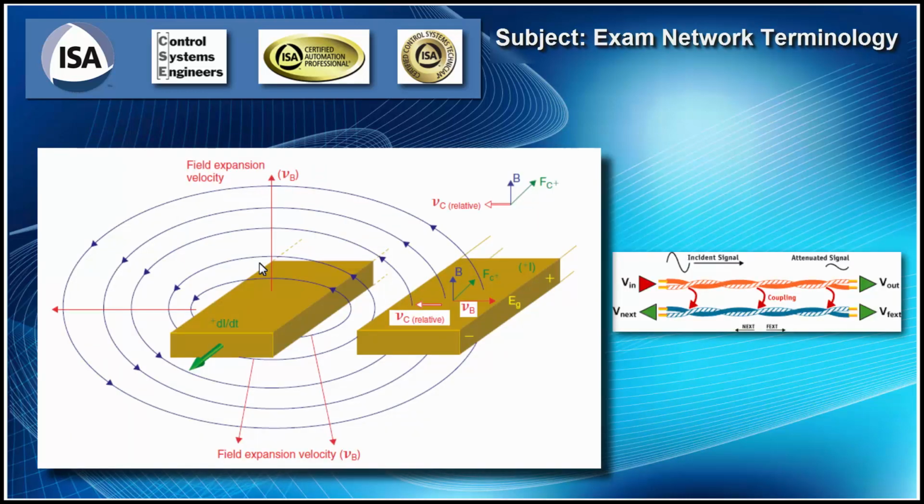The other thing I want to talk about is crosstalk, which is in the specification. Crosstalk is where you have voltage interference going into the transmit and receive, and it causes corrupted data, so you just have to resend it. This can be caused by the lines, or by EMF or RFI from radio frequencies around you. In wireless, it can be caused by too much congestion on the same channel. So if you're having problems with wireless communicating and you keep dropping packets, the thing to do is change to another channel.